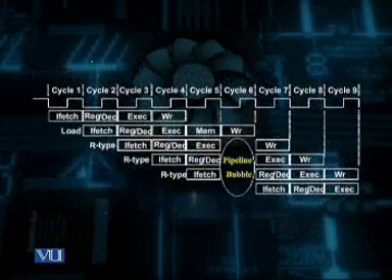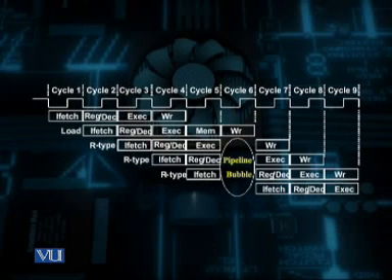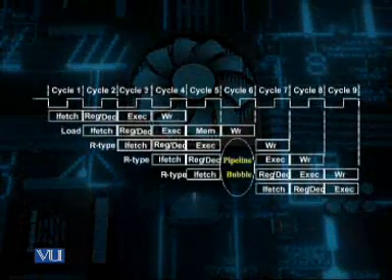Bubble, as I am using this terminology for the first time, is in fact a stall operation, which means that we stop the operation for one clock cycle and wait till the end of the clock cycle, and start at the tick of the next clock cycle. And then the required write operation starts.